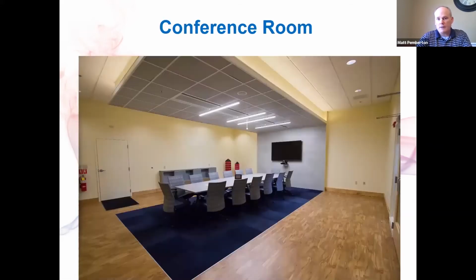Offices. Here's a good example of a conference room. You'll see the chilled beam down the center of the space here. The reason we talk about this conference room application is that typically chilled beams are a constant volume system. When we talk about laying out an office, there's going to be that corner boardroom, that corner conference room that's going to have a high sensible load, high occupancy, but then no occupancy. Say a conference room may get 1 hour of occupancy a day, and so we want to variable air volume control that space. How do you do that when you're implementing a constant volume chilled beam style system? So the question is, can you VAV control a chilled beam system? The answer is yes, and that's the purpose of pointing out this conference room area.